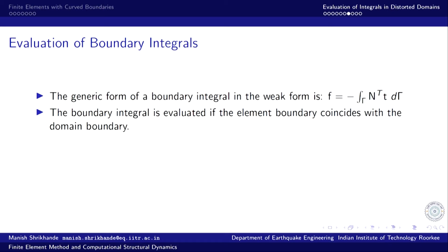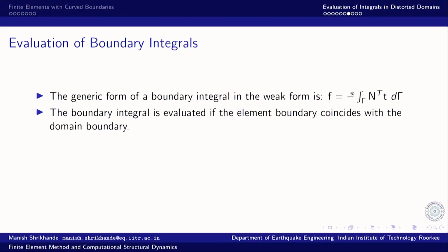and the boundary integral is only evaluated if the element boundary coincides with the domain boundary, because in the interior of the domain, the element boundary integrals would be cancelled out by the corresponding contribution coming from the adjacent element, because these boundary integrals are always to be evaluated while traversing the boundary in the counterclockwise direction.